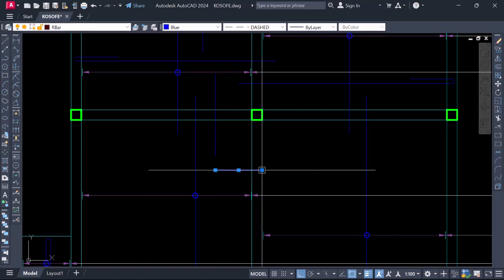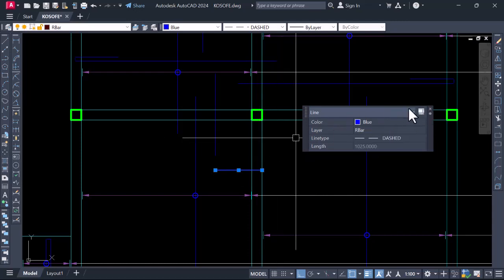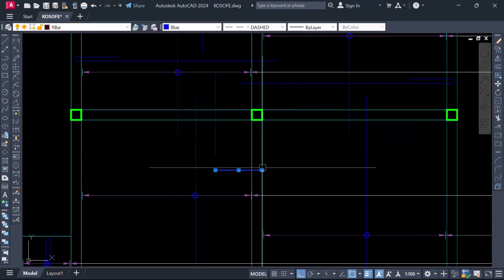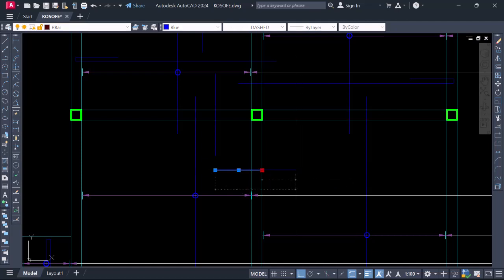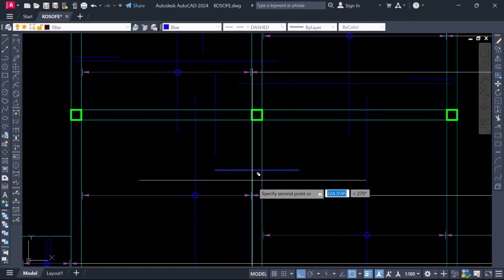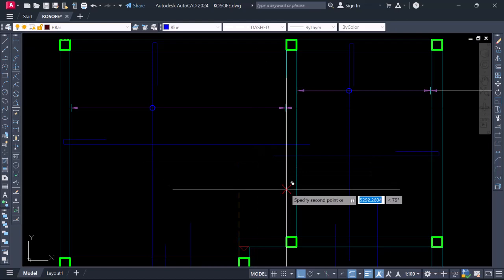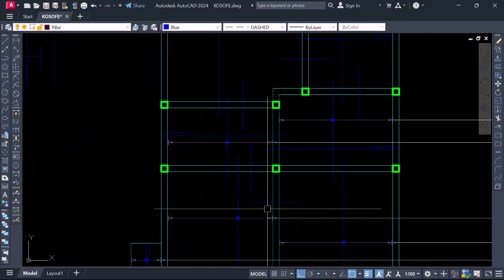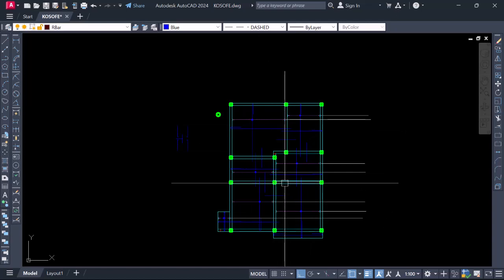I'm going to take this over here. I'm going to cut A3 across 800. Sorry, let's get rid of this. So I'm going to click here. I'm going to take 800 millimeter. I'm going to copy this to this other span. Mind you, what I do here is because I'm having a simple slab detail like this. I'm going to have a simple slab panel.